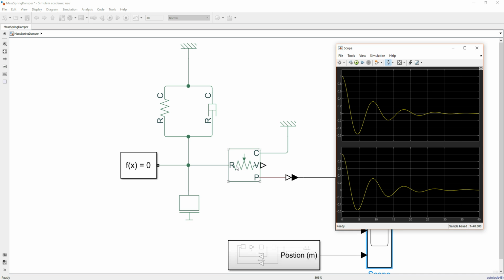Now, the most interesting one I'd seen for a double mass spring damper is an earthquake detection. This is incredibly cool. Well, I don't mean what it's for. The lower earthquake detection will pick up noise. And if the lower one begins to oscillate so strongly, the noise then transfers to the second one. This then causes the actual thing to really, really vibrate. This is where your Richter scale comes from. It comes from the second, because the lower one cancels out the noise, but the upper one will record true deflection of what's occurring. And it's just very, very impressive.